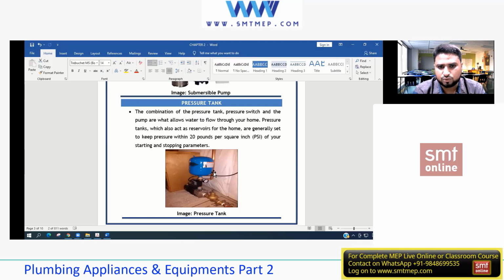Yes, either we need to connect this in series. But if I connect in series, first of all, I'm investing in two pumps. And second, I'm utilizing more electric power, and that leads to what? The running cost. Yes or no? Yes. At the same time, the pump might need quick maintenance because its working load is more, isn't it? For example, it might last 5 years, or it might get into trouble in only 1 year or 6 months. It needs regular checks, and it might need maintenance.